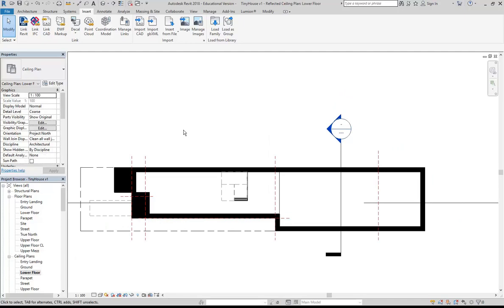Now, have you drawn a ceiling plan in any of your other classes? So, sorry, I should call it RCP, reflected ceiling plans, yep. And it's good to use that full term because that term reflected really tells you how these drawings work differently to a regular floor plan. They are a reflected view, which simply means that it's like you've got a mirror on the floor that's reflecting what will be on the ceiling above.